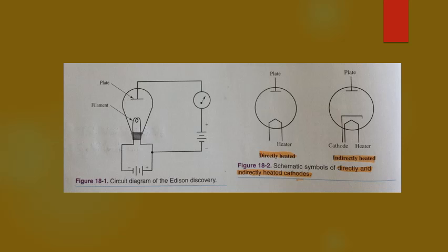Equipment that uses batteries for power works best with directly heated cathodes. There is less heat loss, and the filament can be designed so that only a small amount of power is consumed during use. When an AC source is handy, the indirectly heated cathode is more practical. There's little power loss, and the heater voltage source and cathode can be separated. This eliminates any humming in the circuit.